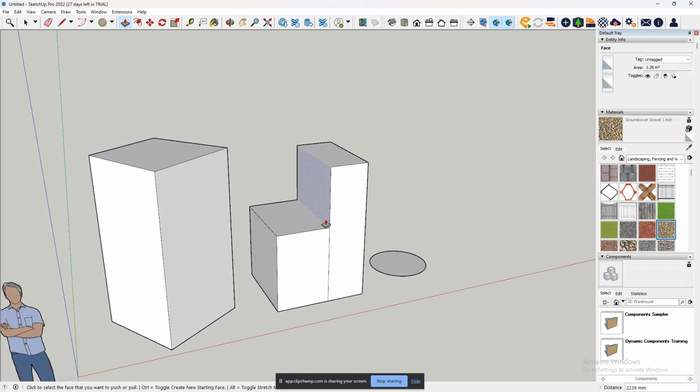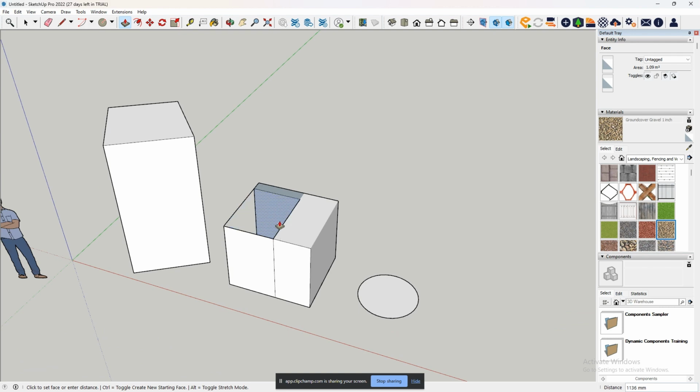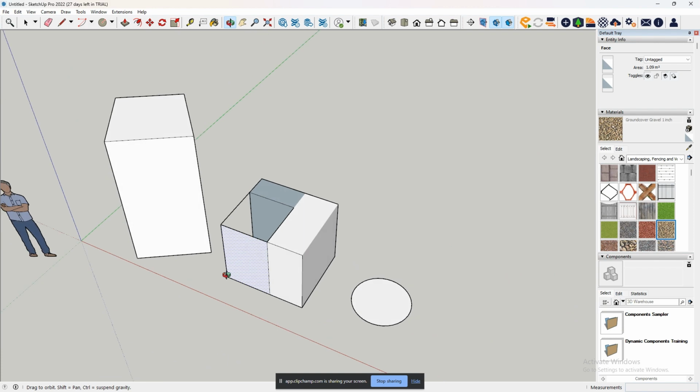For example, the more you push-pull, the more you'll have different surfaces pop up, like this new surface here. Now, as I said, push-pull is good for creating 3D objects, but it's also good for erasing separate parts. You can almost use it like a cutting object, because if I hold on to this and drag it all the way here, you'll see it once again hits this offset. However, if I let go of my mouse now, it completely shaves that part off, and now you have a smooth surface. And you can do this almost indefinitely. So see, that is to do with that Control issue.